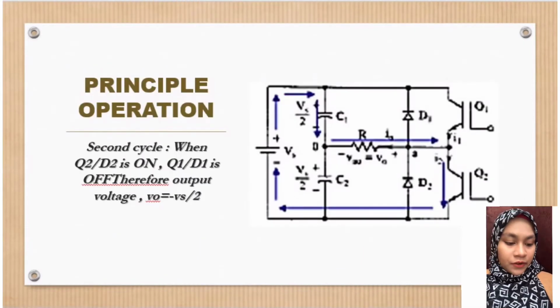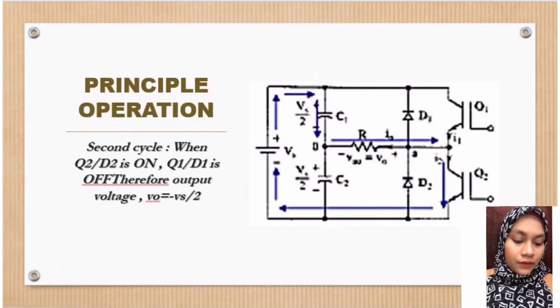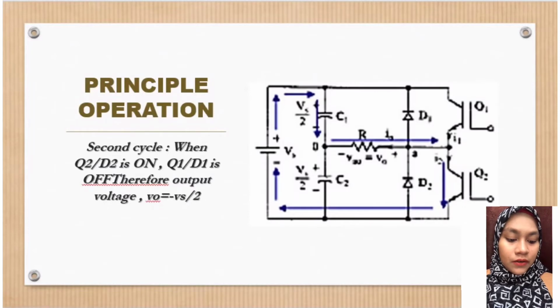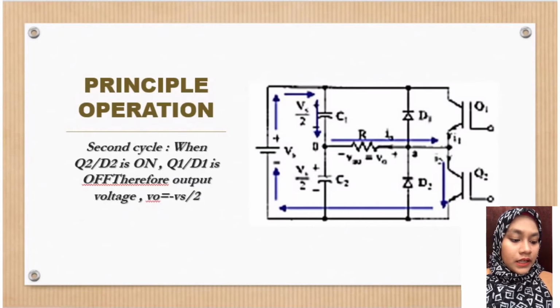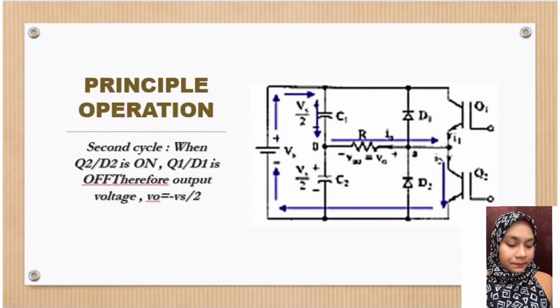Then, for the principle of operation of the cycloconverter, the equivalent circuit is shown in the figure below. Here the two-quadrant phase-controlled converter is represented by a voltage source of the desired frequency, and we consider that the output power is generated by the alternating current and voltage at the desired frequency.